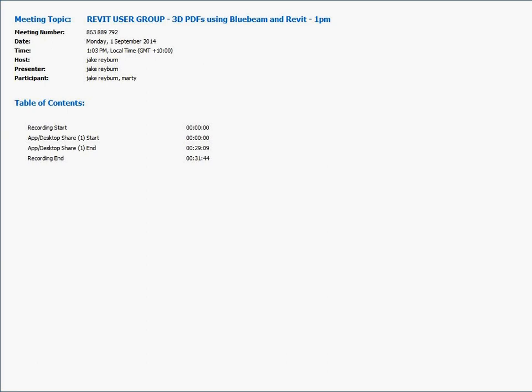Any other ideas? One would be the view range, not just the basic flat one that's stepped, because I'm having an issue with my models because the basement's so stepped. It has to be dead on, otherwise it will show parts of basement 2 on the plan of basement 1, because they're really close to each other. Did you try using plan regions? When we set the project up, it just stayed the same as that. You know we can do that, don't you?